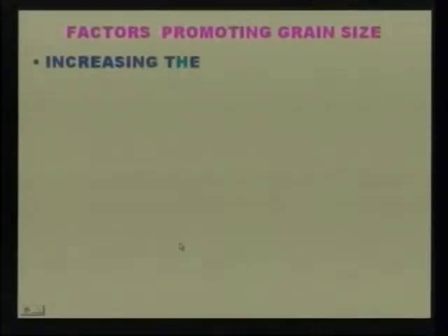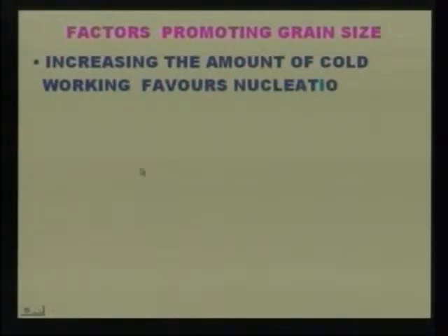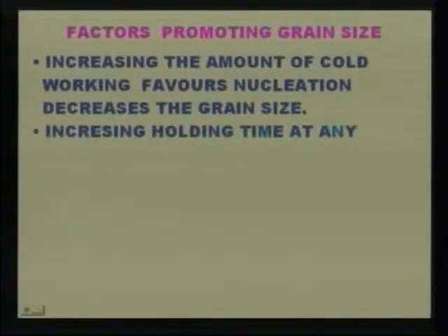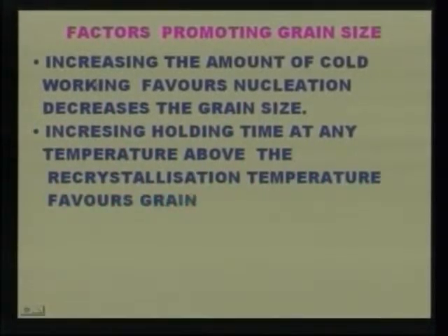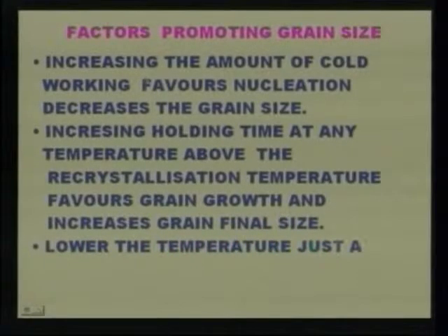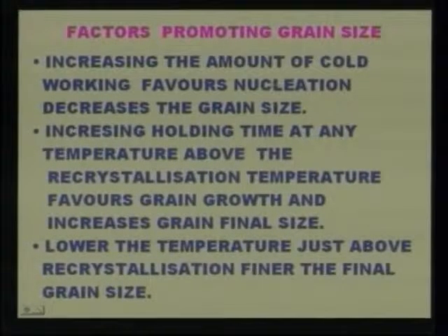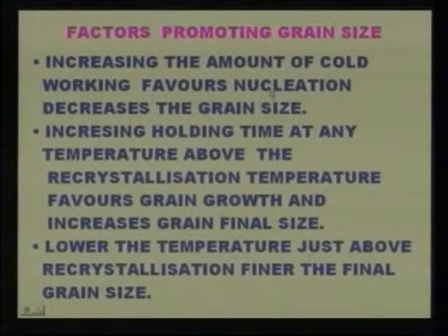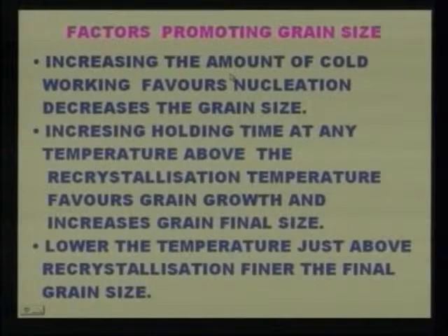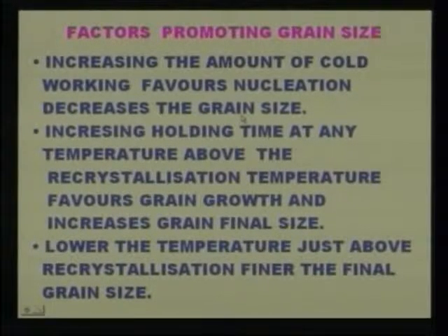Now let us see what are the factors affecting grain size. These are the factors we can see. Increasing the amount of cold working favors nucleation and decreases the grain size. So by increasing the nucleation, we can increase the number of crystals formed, which promotes the fine grain size and decreases the size of the grain.